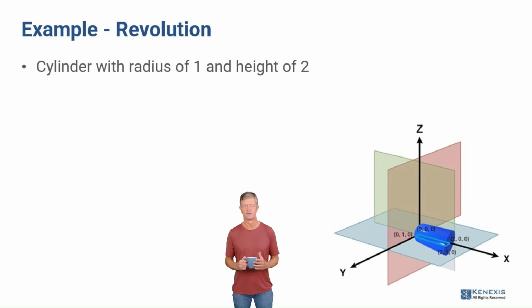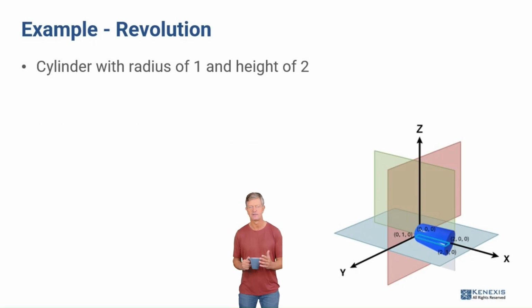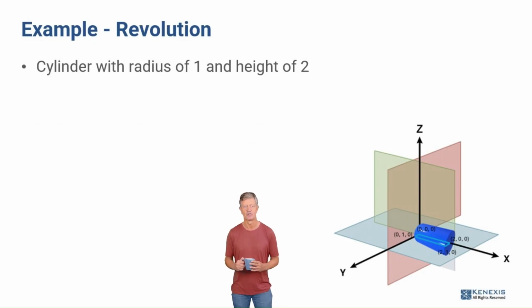Next, we need to define a line to rotate the object around, or an axis of rotation. To represent a line in 3D space, we can use the parametric equation, which defines a point that the line passes through, and a vector which represents the direction of the line. The angle of rotation is simply how far around the axis of rotation you wish to rotate the polyline. If a full rotation is desired and units of degrees is used, the rotation would be 360.